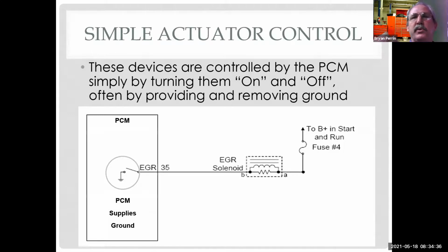A lot of times we do these tests in conjunction with a tool that I can talk to the vehicle's computer and say, hey, can you turn this on 100% so I can test it? I can't do that with all my actuators, but I can do that with some, depending on the manufacturer and the scan tool. If I don't have that option, then I would need to test this under conditions where the computer would turn the EGR on. So now I need to understand how the EGR system works.